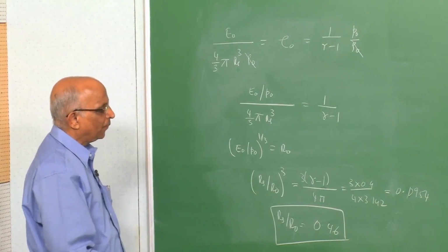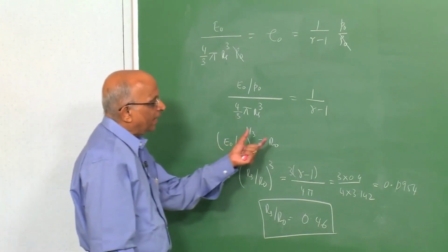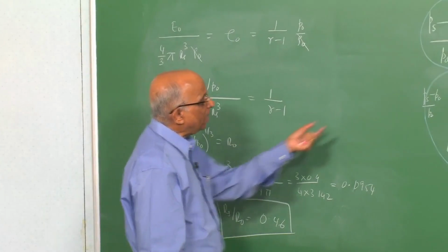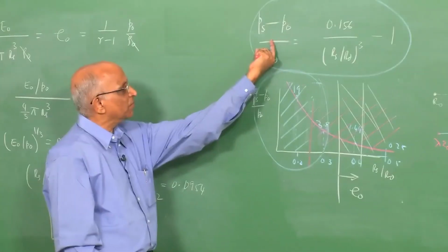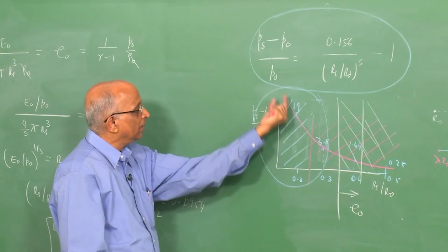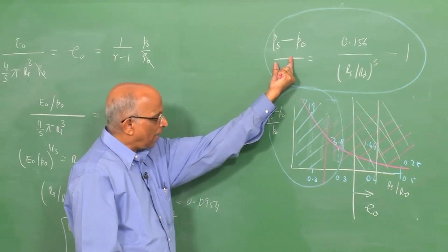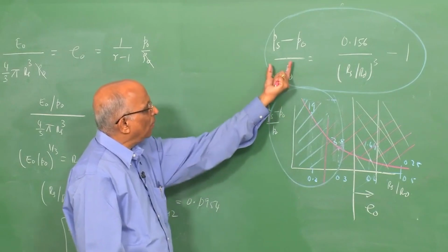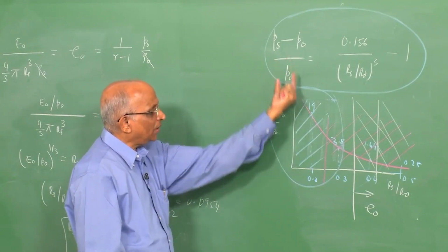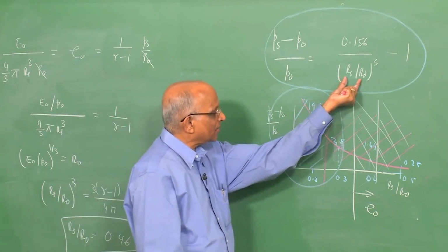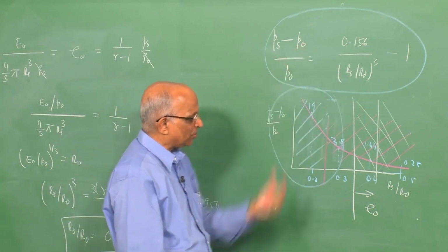This is where I conclude today, and to put things in perspective, what have we done? We have looked at the energy conserved by the lead shock wave. We have been able to get an expression for Ps, that is the overpressure of the blast wave. In addition, we talked about the Cranz-Hopkinson scaling law and the Sachs scaling law, which gave us this expression.